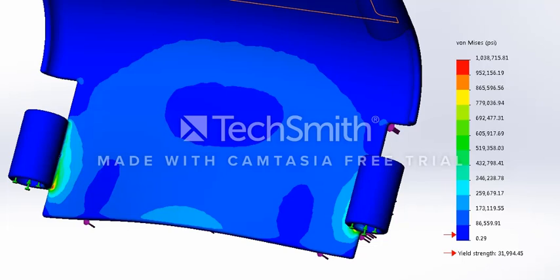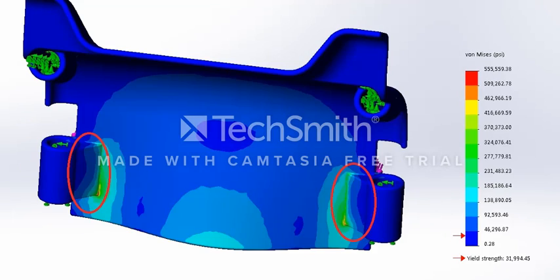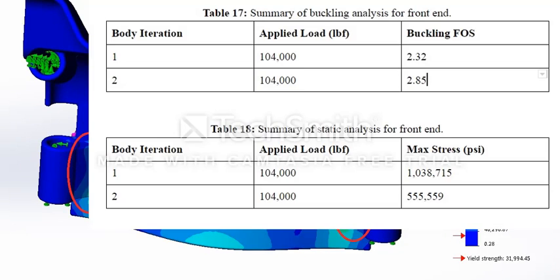The front end was then subjected to a static analysis with a reduced load of 26,000 pounds. The results show that the part yields. To help with this problem, triangular supports were added to reduce the max stress. However, this is still far above the yield strength of the material. In order for the part to not yield, we would have to drastically increase weight.